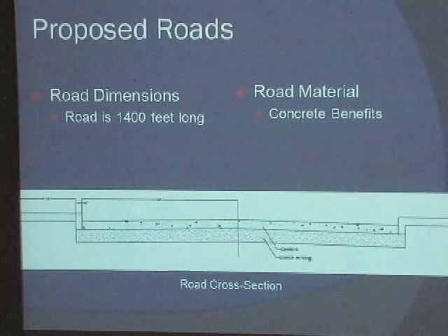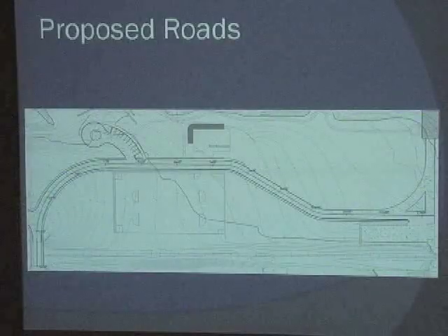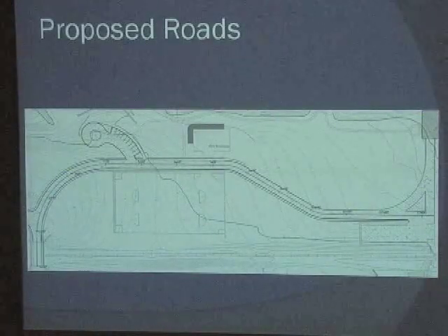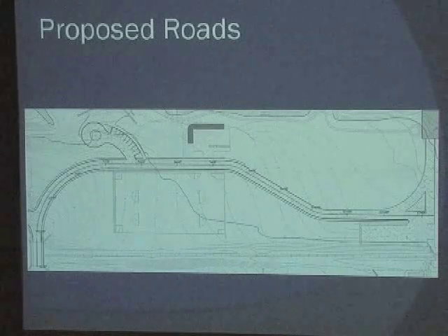Some benefits of using concrete are that they have a longer service life of 40 years instead of asphalt for 10 years. They need less maintenance if done properly poured. Is resistant to oil spills in vehicles and extreme weather, and also vehicles use 15 to 20% less fuel on concrete roads than asphalt. One of the requirements for our site is to have access to the neighboring community for